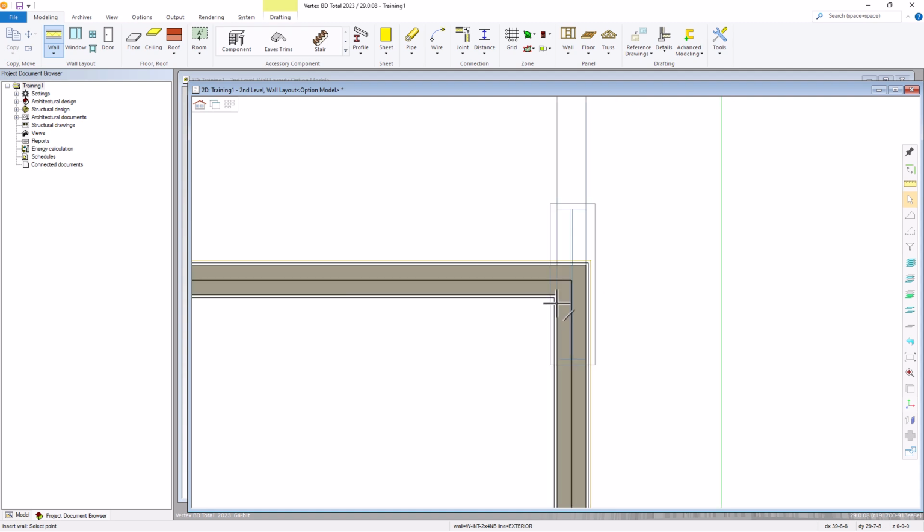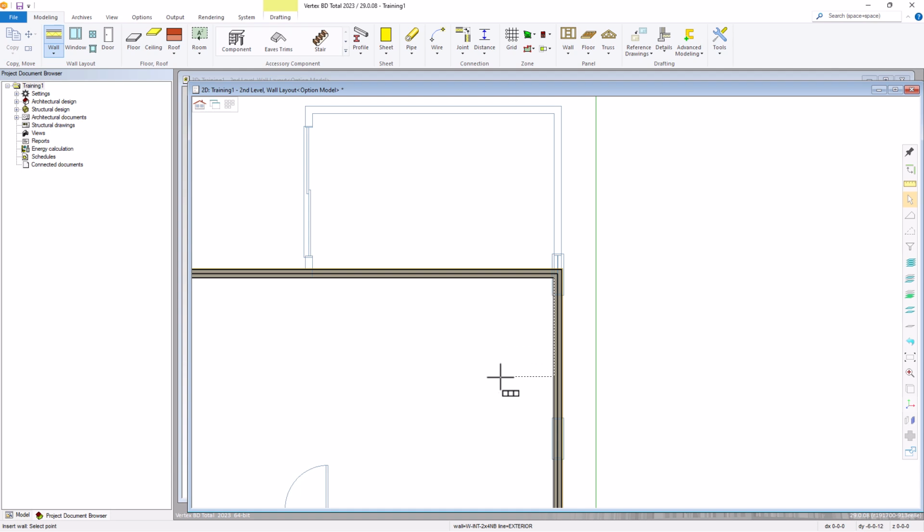So we'll zoom in on this corner, get that yellow icon. We'll hit the letter Q to set our reference point. Select the I key to lock the constraint in the Y-axis or vertical. Bring that down and type in 8 feet 10 or 8 foot 10 inches.